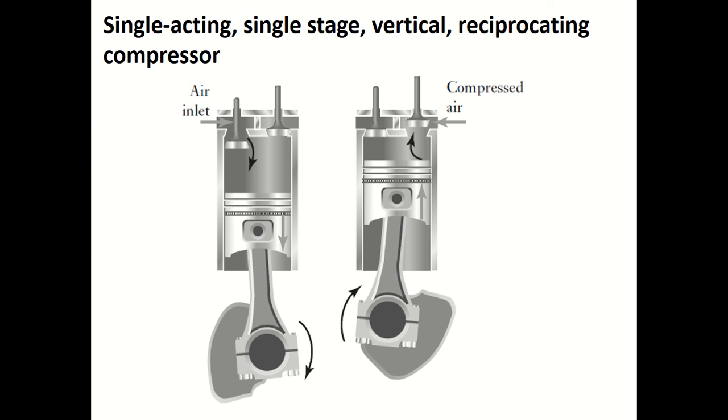When the air pressure reaches a particular limit, the spring loaded outlet valve opens, and the compressed air flows into the compressed air system. Please note that after the piston has reached the TDC, top dead center, it then begins to descend and the cycle repeats. Such a compressor is termed single acting because one pulse of air is produced per piston stroke.